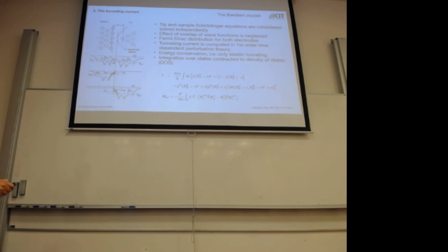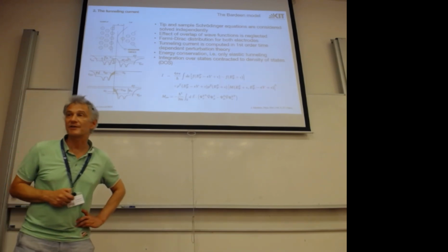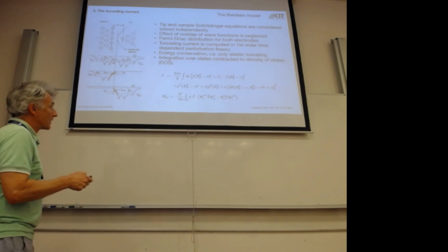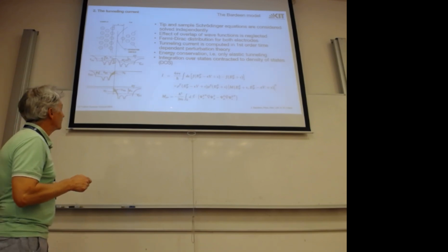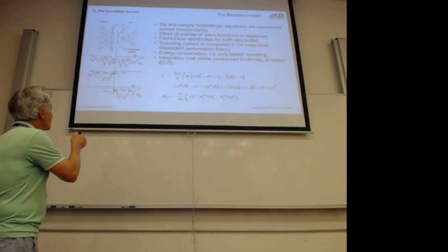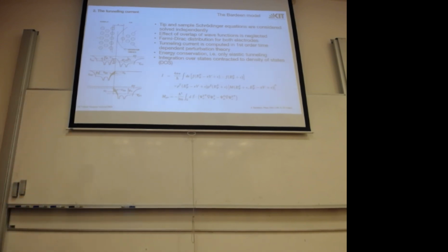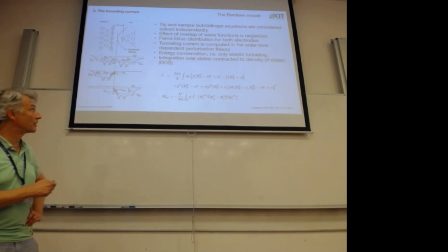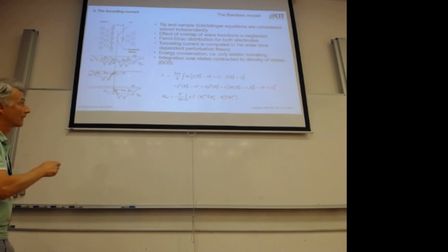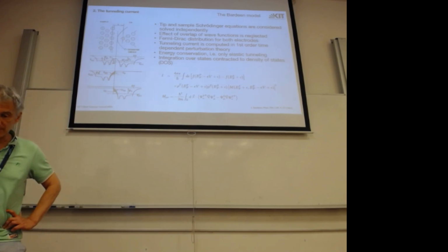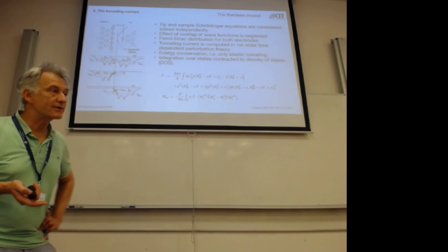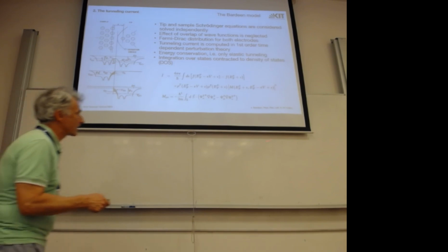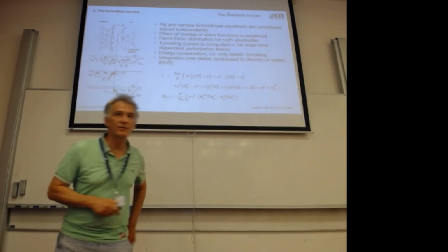So this is, to first approximation, featureless. It's the same for all electrons, which is not exactly true. But this matrix element can be computed on this imaginary separation line by the flow of the wave function. So it does not matter actually where you put this line. The separation surface will always give the same answer. This generally is true for any planar junction. And it was calculated by Bardeen, in '61.